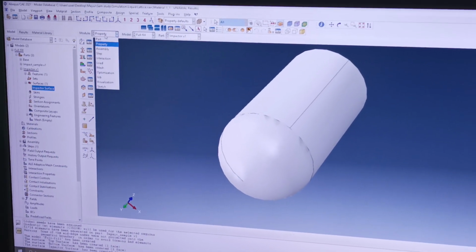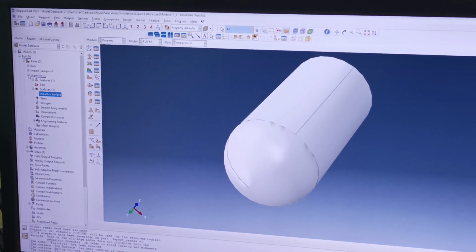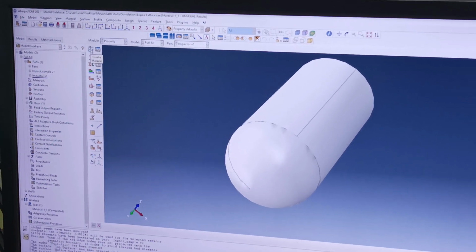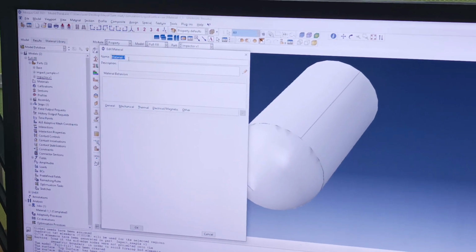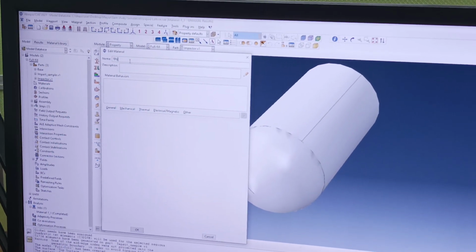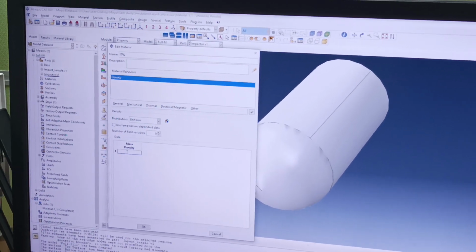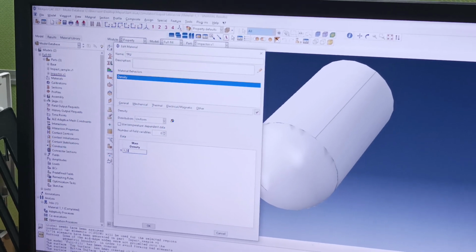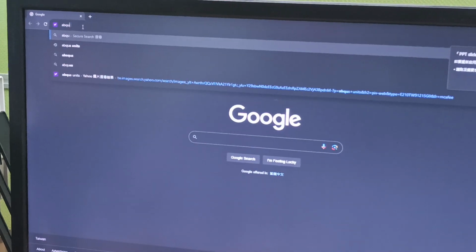Okay. Let's go to the property menu. In the property menu, we need to first define the materials. So you see this, create a material. Click on create, then we come to this window. In our case, we have TPU. So I just write TPU, and the TPU density is around 1.23 gram per centimeter cube. But in Abaqus, you need to follow the units because Abaqus does not have units. So always take a reference.